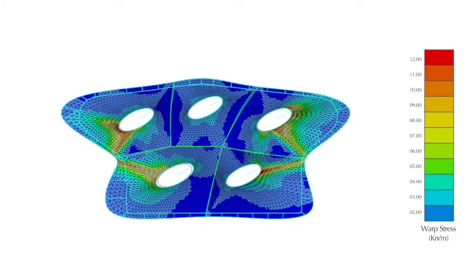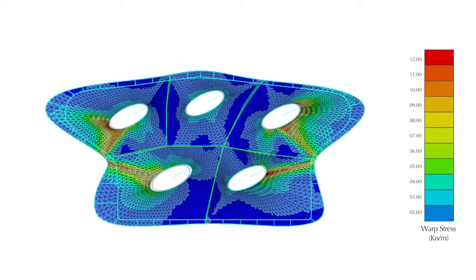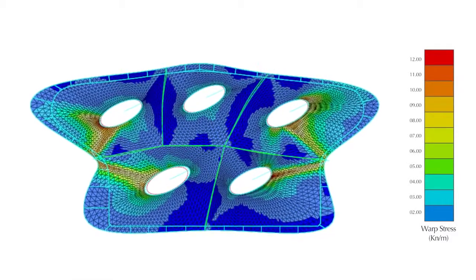The strength of a fabric structure and its ability to resist loads comes predominantly from the tension at which the fabric is maintained. Because of the nature of tensile structures, they have to be heavily engineered. I can provide picturesque designs, very flowing designs, very attractive to the architect, to the client, but I also have to make it work. There's a very large load in this fabric skin that is going to be transferred somewhere, whether it's contained within the structure itself or whether it goes back to the ground, whether it goes back to the surrounding building.